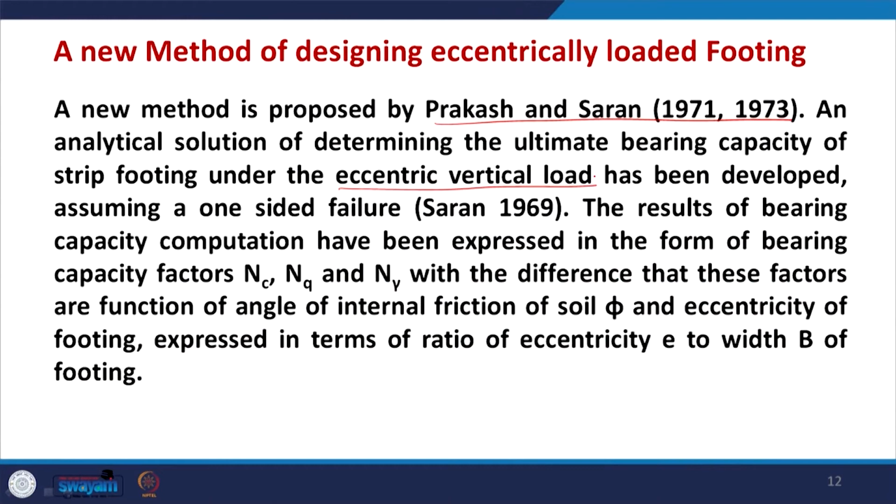The results of the bearing capacity computation have been expressed in the form of bearing capacity factors Nc, Nq and N gamma, which not only depend on the angle of internal friction phi, but also depend on the value of eccentricity e.